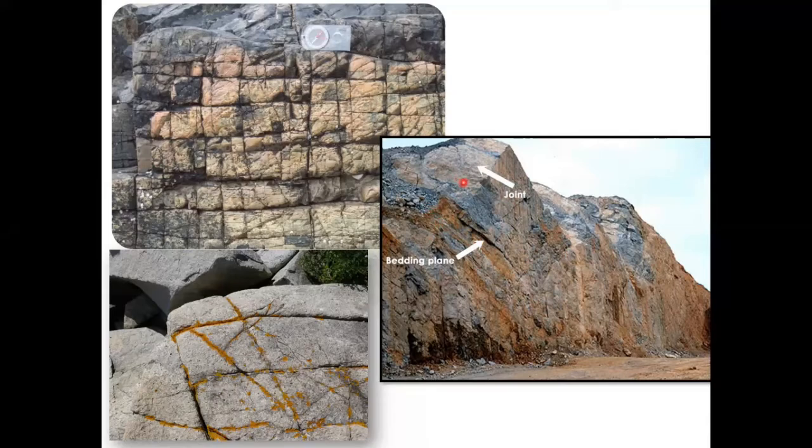Is it changing the orientation of bedding planes on the other side? Is it producing some kind of slip and offset? If not, then you can basically measure strike and dip of the surface and make a note and say it is a joint cutting through bedding planes.